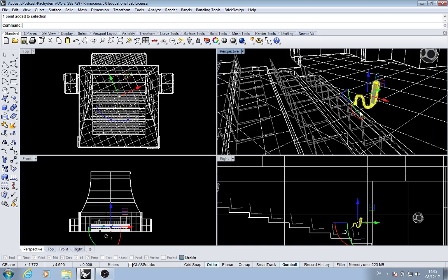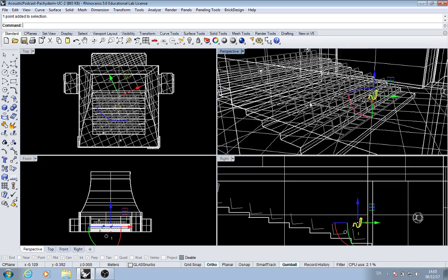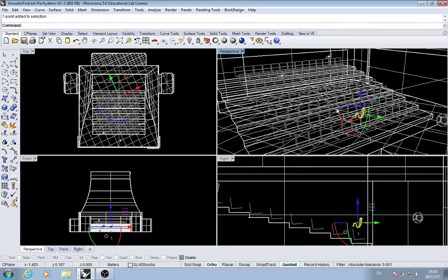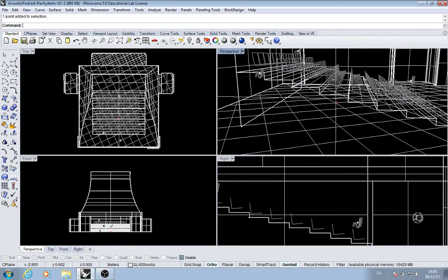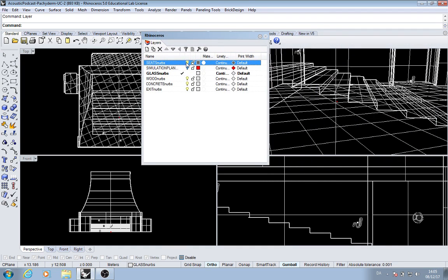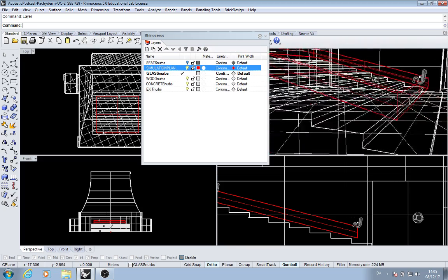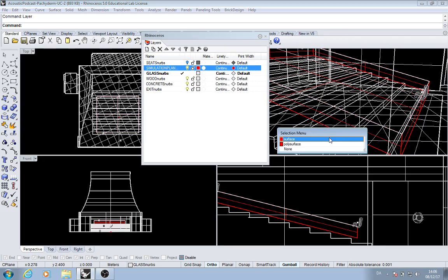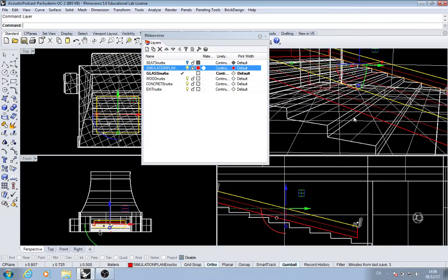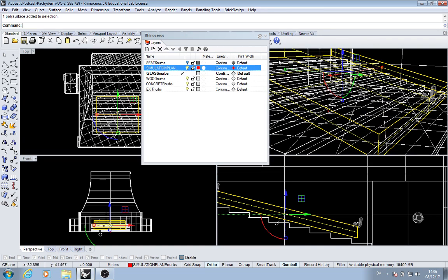So rather than looking at specific points in space, we will look at a surface, which in this case is the whole region, the whole area where the audience is sitting during a lecture or during other events in the auditorium. We can see we already have the seats in here. But following the industry standard, instead of having seats, we will have an area which includes the seating and the potential occupancy of the listeners in the space. In this case, it is constructed by a surface on top, which we will use to map the results from our simulation onto, and a volume that defines the properties for this zone in terms of occupancy.